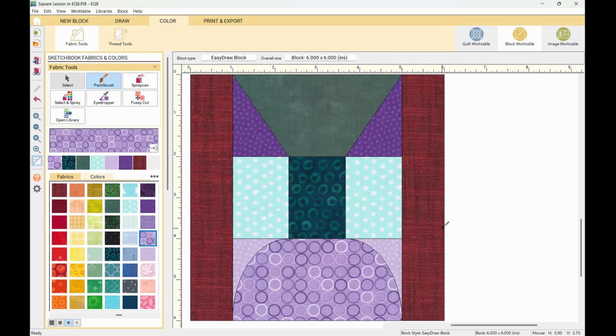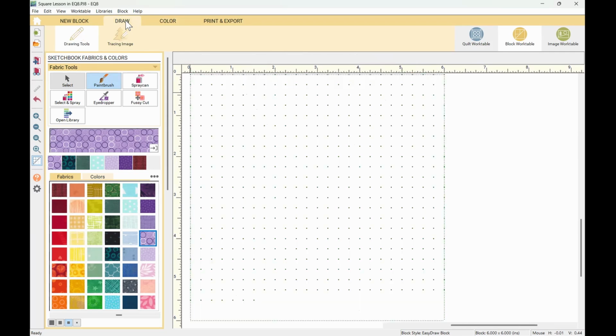So the color stays in there. And what usually keeps you from doing the color correctly is you got some invisible disconnect between the 2 lines. Right. It looks like they're connected. It looks like it's snapped to the nodes, but you didn't have it set on snap to the nodes, so it's not quite. And it's very frustrating. Right. So like I was saying, check it out with the color after you draw it. All right.